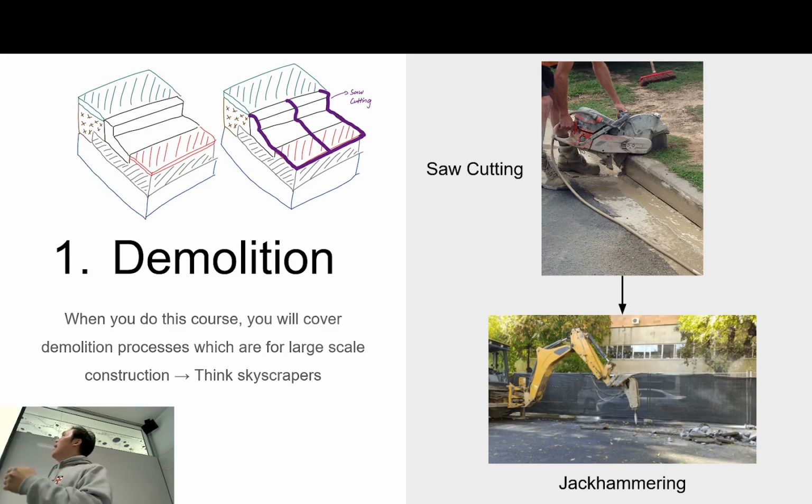So the reason that they have water pouring out into the saw is, number one, for heat management, because cutting concrete is really, really tough and it takes a long time. Right? So the blade will heat up and warp if you don't put water in it.